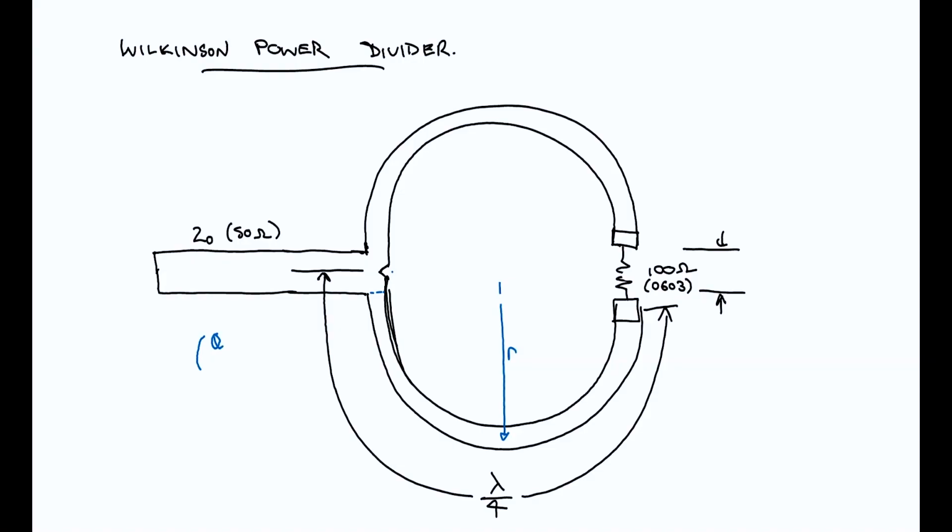That didn't come out for some reason. Let me just trace over that, 2 pi r. So this is our length. So that equals a quarter wavelength, right? And because this is 180 on 360, that simplifies and cancels out the 2. So we have half times 2. So that equals pi r in degrees. So from there we can work out r is, of course, wavelength on 4 pi. So that's the rough starting point. It's a bit unclear, but you get the idea.